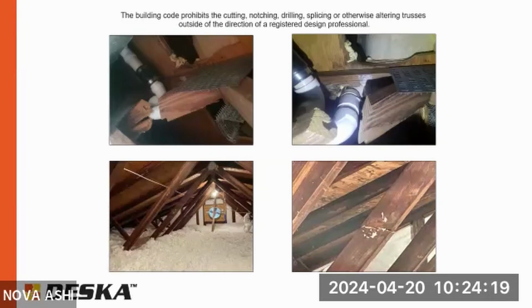Are framing contractors knowledgeable enough or skilled enough to devise a repair? For a truss, no. Not a truss, but for say a rafter or a floor joist, yeah, I would generally say so. I wouldn't necessarily recommend that, but I would generally say so. At the end of the day, you could do a full length sister, and now you've essentially replaced that member. That would generally be an adequate repair as long as moving the structural member over 1.5 inches or so doesn't cause an issue.